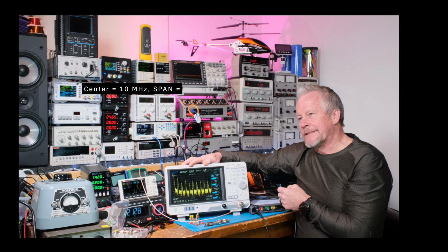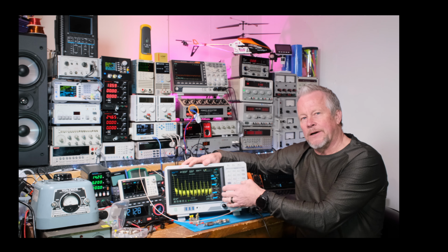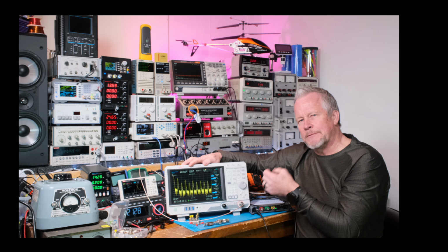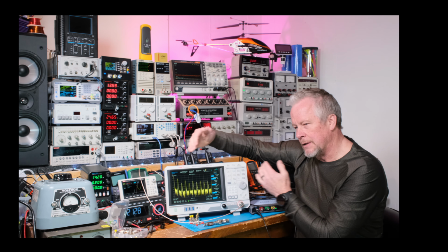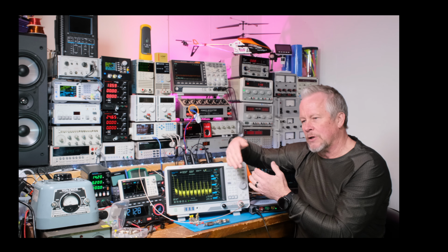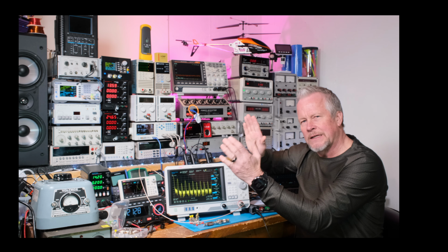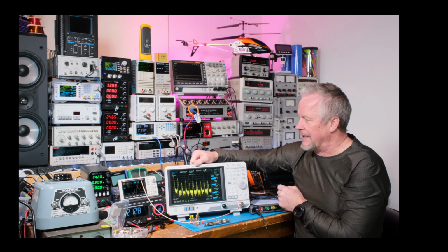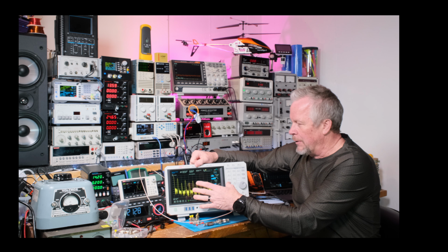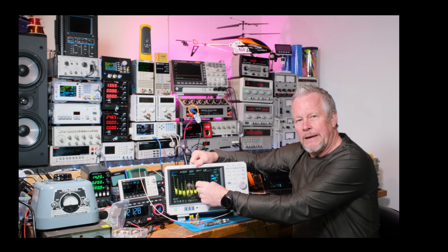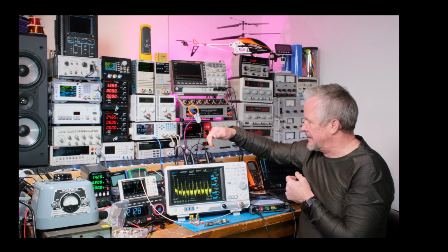The reason spectrum analyzers use center and span is because a lot of times that's what you're thinking. You're like, oh, I want to look at this frequency, but I want to look at these side bands. I want to look at the frequency, this many frequencies before and this many frequencies after. So I want to look at the span. It's kind of like in an oscilloscope frame of thinking where you go, I want to look at this and then zoom in and zoom out, like on a touchscreen. You can pinch and pull it, like on my mixed signal scope back here, okay?